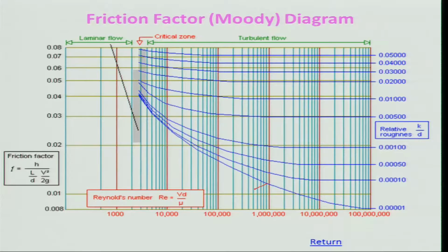If you look at this, it is a smooth region, almost negligible, you can say. There might be another place where it is smooth. So, if you look, these are all converging, and as the roughness increases and the Reynolds number is higher in this region, the friction factor is not changing. There is no change in this region, the friction factor remains constant. That is the beauty of it.